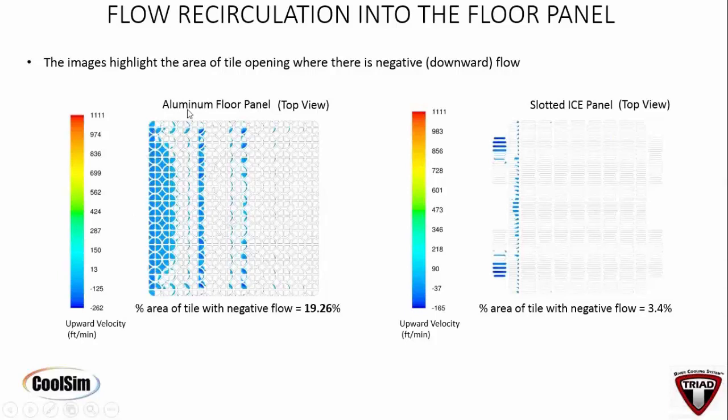So what you see here on the left is, again, the 56%er. And we're showing velocity in feet per minute, both positive and negative. So we wanted to show off the recirculation here. Look at it. It's that leading edge, and this is exactly where you put your velometer when it went negative. And that's what we're seeing.